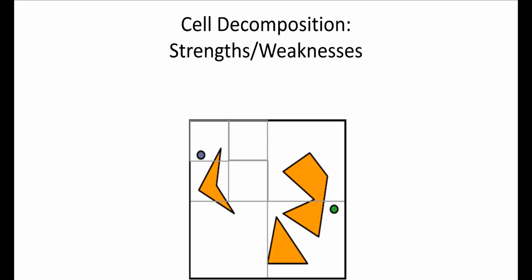So when do you limit the split? That's a good question. You could stop decomposing when there's a path. You could say that with this algorithm, you stop when your cell size becomes smaller than your robot, right? In that case, your robot couldn't navigate the gaps anyway, so why compute them? But that's a design decision that's up to you, and poor choices there can limit the applicability of your algorithm.